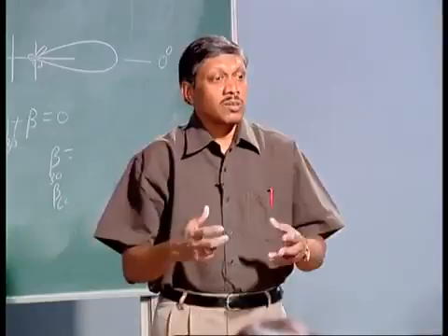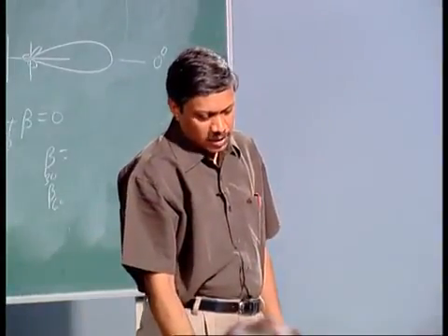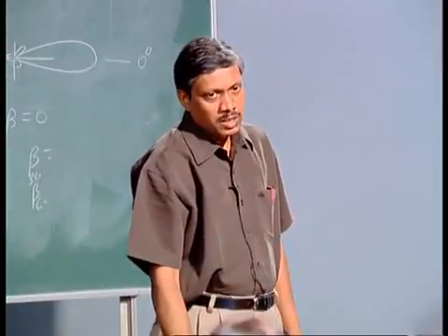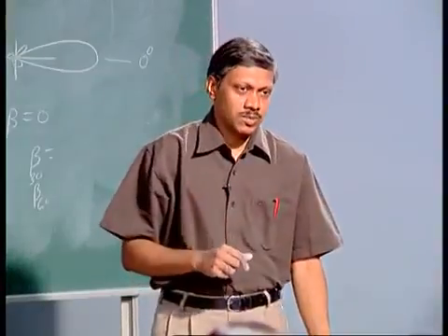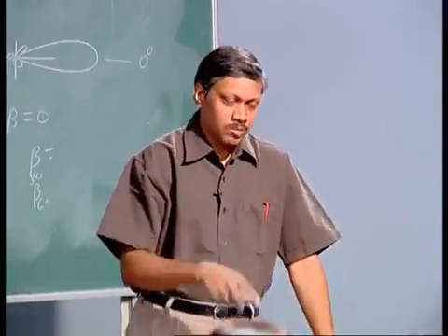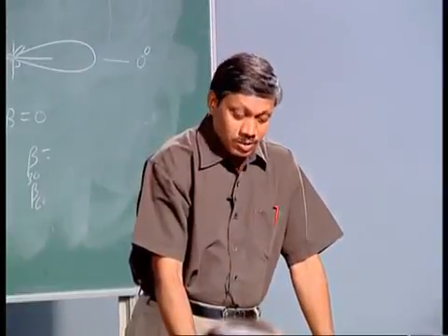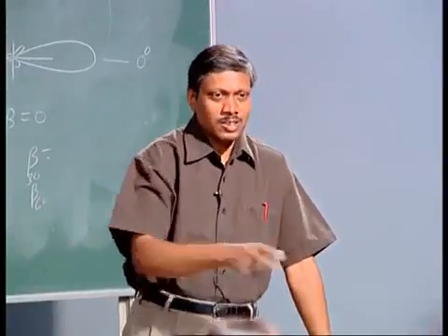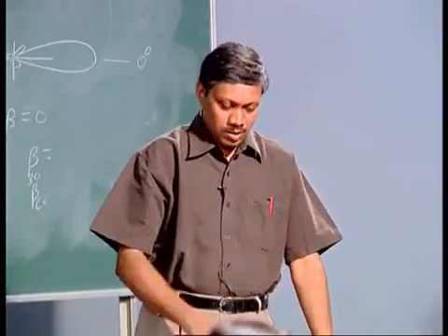Alright. So, you have a phase shift scanned array. The array is scanning the space, and the beta is being controlled as minus kd cos theta. So, as per your theta requirement, you go on varying the beta value, because once the array is fabricated, your d is fixed. So, d you cannot change. There are some new approaches where d can be changed, which are the recent reconfigurable antennas that we have discussed; we will discuss them later on, once I finish this.